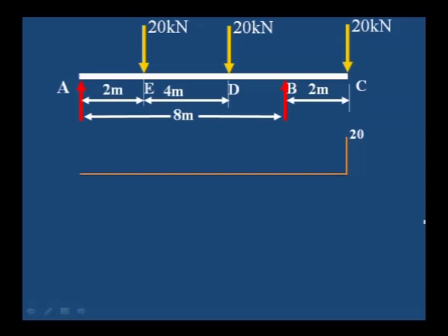While drawing the shear force diagram, first you draw the horizontal line, and then at C there is a 20 kilonewton vertical rise equal to the point load, and it remains constant up to B. It changes to a negative value, minus 25, and then it remains horizontal, constant up to D, and then it is reduced to minus 5.